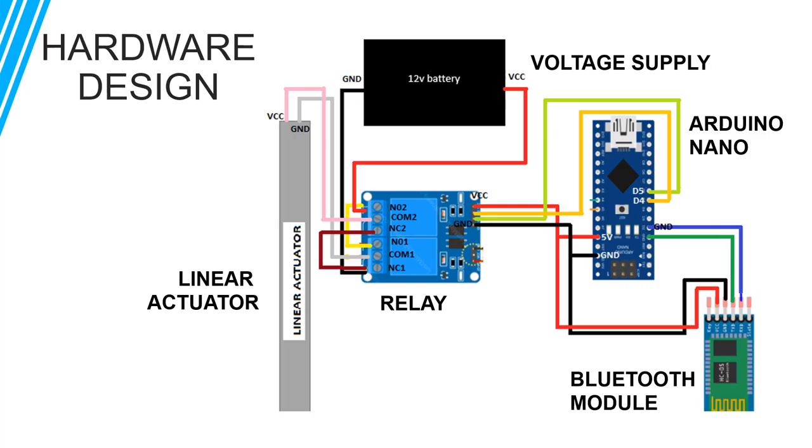A central control system named Arduino Nano will interface with an HC-05 Bluetooth module and a two-channel relay single pole double throw. Digital pin number 4 and pin number 5 from Arduino Nano will be connected to input 1 and input 2 of the two-channel relay. In addition, pin Vin or input voltage and ground are also connected to the relay. For connection on the relay, we will use a wire to connect from normally open on relay number 1 to normally open on relay number 2.